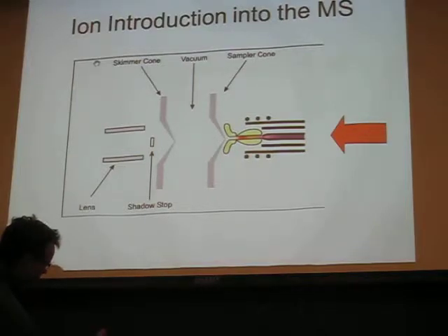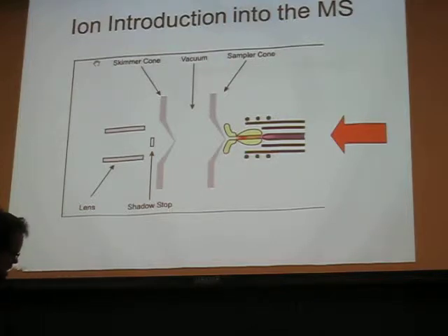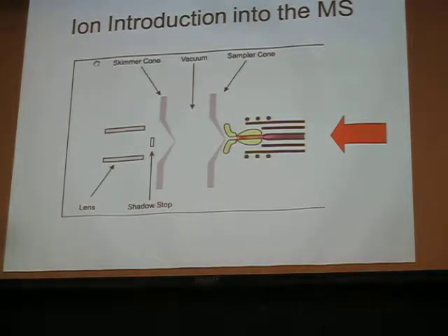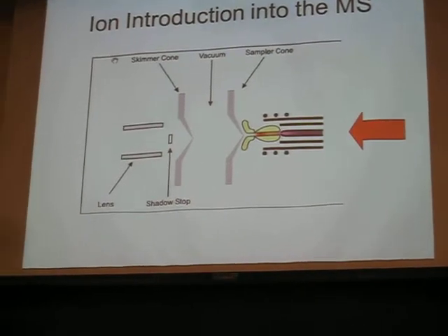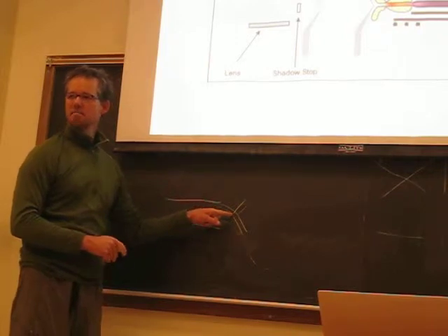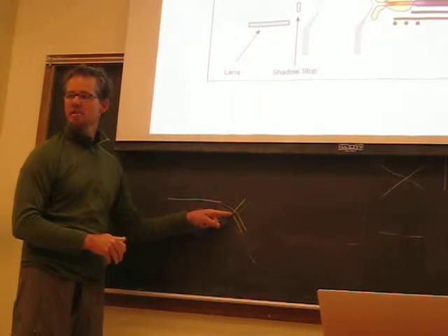For the instrument, it actually has a sample cone, they call it, and then something they call a skimmer cone, which is shown here, that are impinged right up against the plasma. These are made out of some very special nickel alloy metals. So this extremely hot plasma is pushed right up against this orifice, which is maybe 0.5 millimeter in diameter.